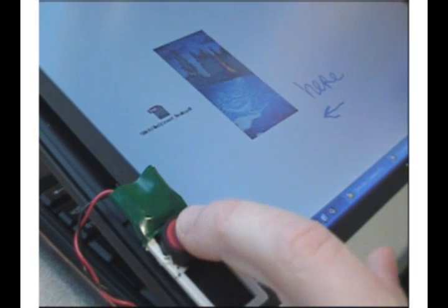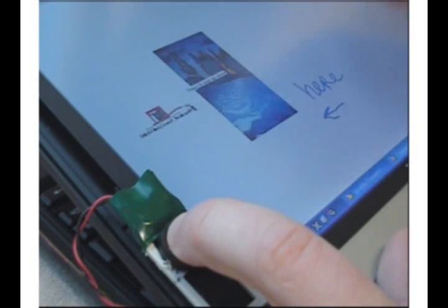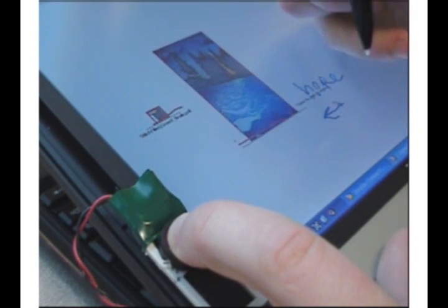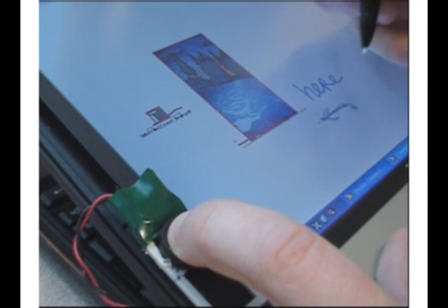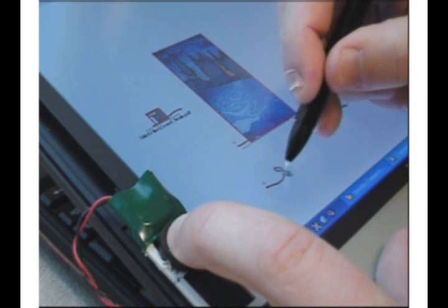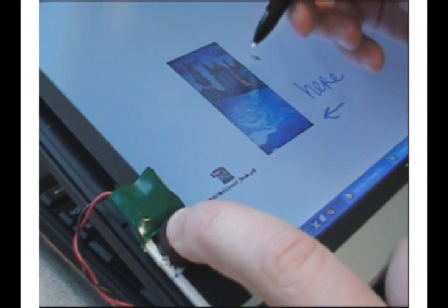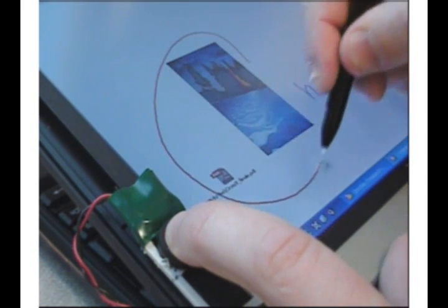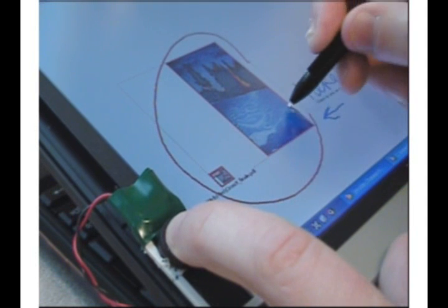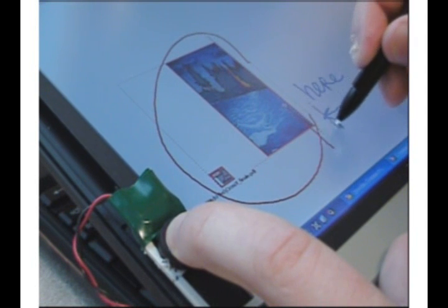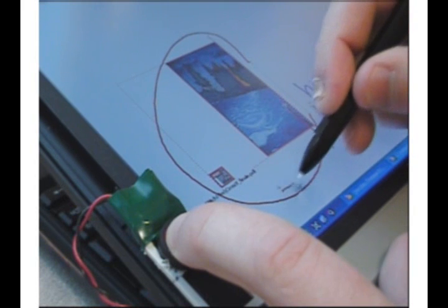Multiple edges of objects can be selected for alignment. Only one align command is needed, since the scope specifies the type of alignment as well as the objects involved. A lasso scope creates an implicit group. This can be used to align objects while preserving the relative spatial relationship between several of them.